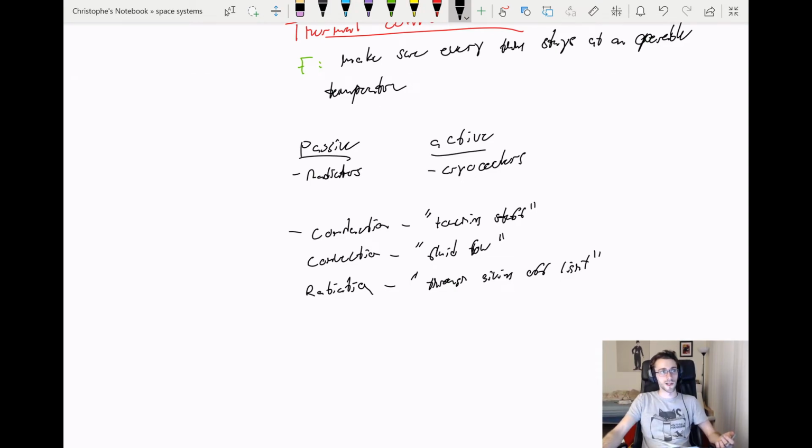But then again, over time, the zinc will actually heat up because you're pumping energy into it over and over. And it's really expensive to get a gigantic block of zinc into orbit. So there isn't really anything to touch to cool yourself off. There's no atmosphere or other fluid flow to cool yourself off with. So you're kind of stuck with radiation as your only method of giving off heat.